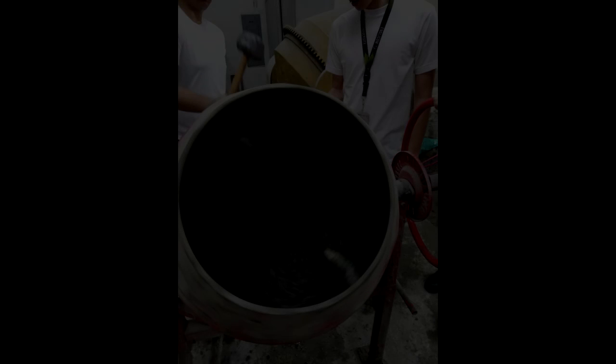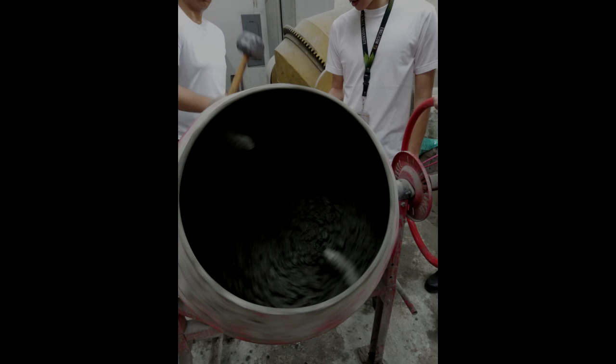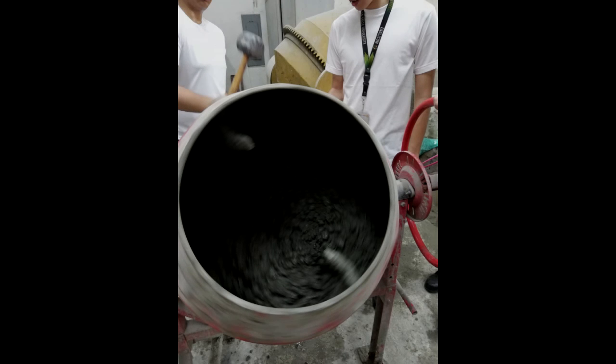Experiment 10 is about making specimens in reference to ASTM C192. Creating the specimens or the concrete cast is essential in the progress of the strength of the concrete. In this process, the molds are filled up with concrete, and this has to be done carefully so as to avoid as many air voids as possible.